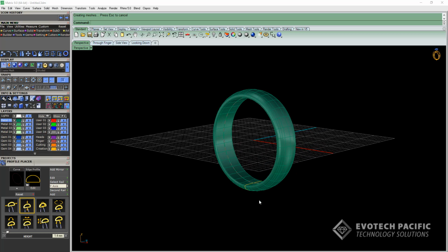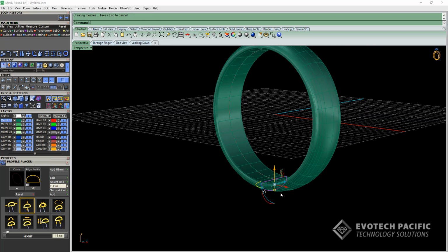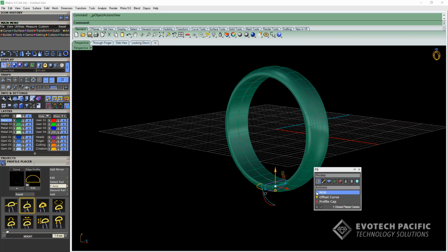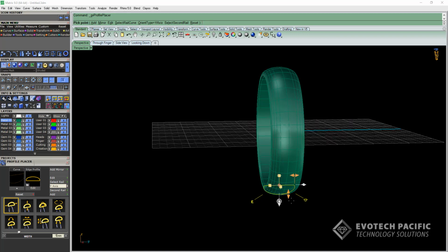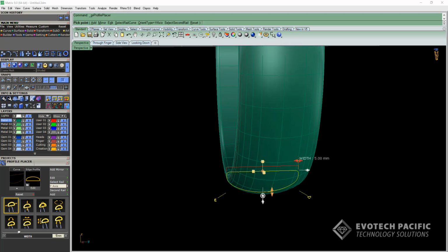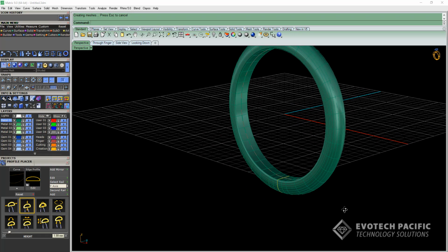The cool thing about this is that we can select our highlighted profile, our yellow profile, and highlight it. Hit F6 or your center mouse button again and go to MSR. MSR stands for Move, Scale and Rotate. So when we click on this, then you'll notice that our handles will come back. And we can change anything about this particular piece because we've used sweep 1 with history. So we can increase and decrease the height and width, and it will automatically sweep for us.